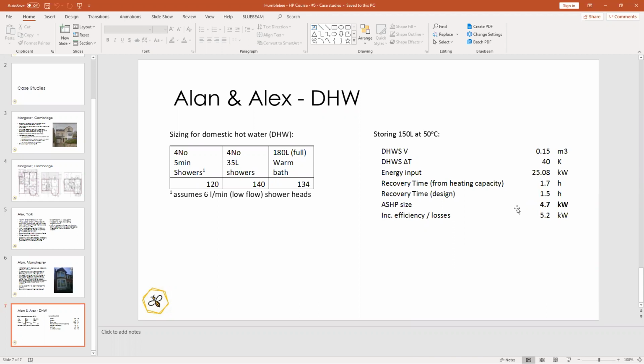Recovery time. Yeah, 1.7 hours is from... When I used the recovery time calculator, it came up with these figures, and I ended up dividing by 3.6, but I can't remember why. It's getting late. It's snowball effects, isn't it? You're starting from cold, but as the temperature warms up in the tank, your delta T is closing. So it actually accelerates as it gets near the end of its process. Okay, that's what it is.